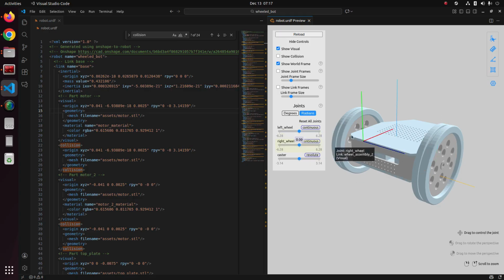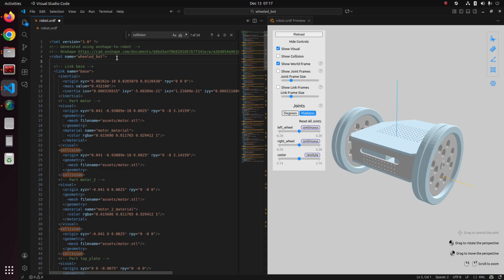So technically you can still use this, but if you want to use IsaacLab's inbuilt functions, then it assumes x is forward, and you're going to have a much easier time if you have the x basically point forward. So to do that, the easy fix is to define an extra link to just define the orientation of the robot.